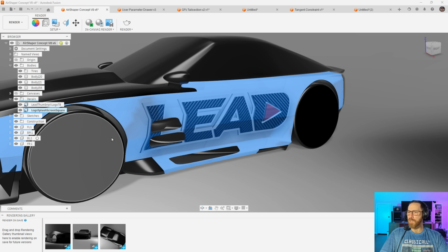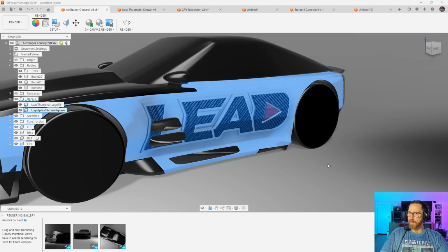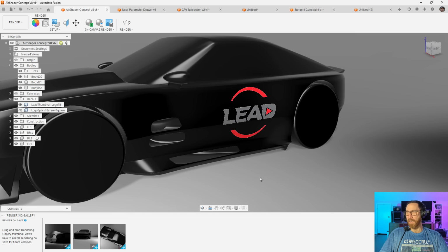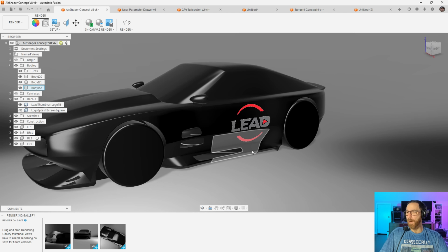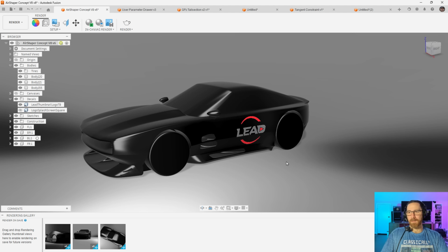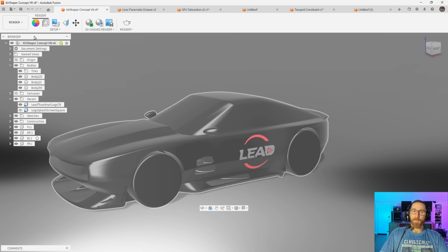So I think it's a good step in the right direction, but I still think that if we could get those to flip visually based on the orientation or the location in this folder, that would really help out, because that's kind of going to be the indicator. If you've got a bunch of overlapping decals, that's going to be something that you aren't going to see until you go to start rendering. And if it's a big complex part or a complex scene, and you're possibly rendering locally, then you could waste some time before you figure out the potential issue.